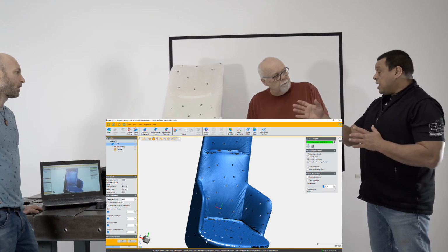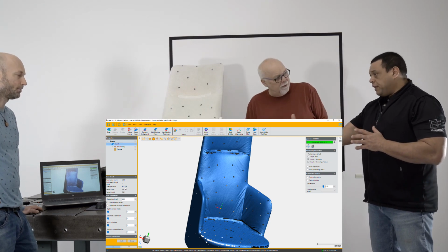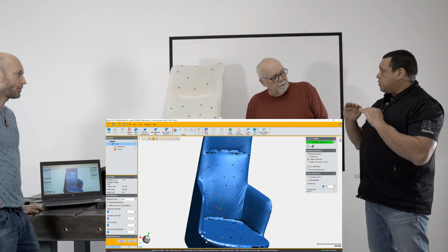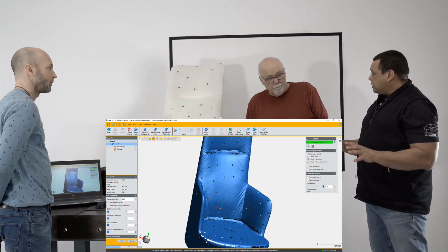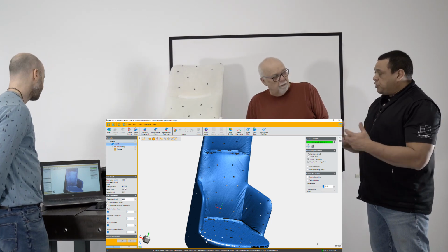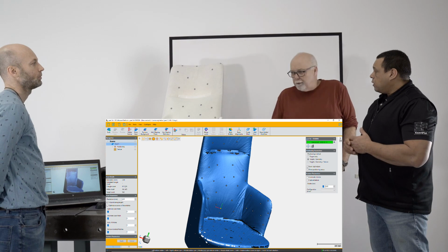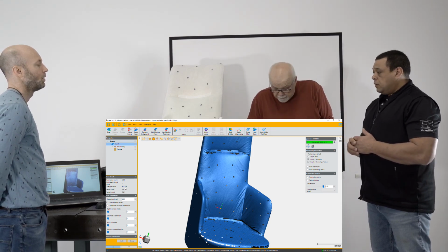I'm assuming that higher resolution meshes cause processing overhead and a bunch of things that complicate your workflow. Absolutely. So you want to get this optimal, and that's just a matter of scanning at a high resolution, the middle, and the low, and then seeing what works. Absolutely, that's part of your first introduction to the scanning process. When you get the feel for it, you'll know that you don't need to scan it at 1mm. But if you're doing something detailed, you might.